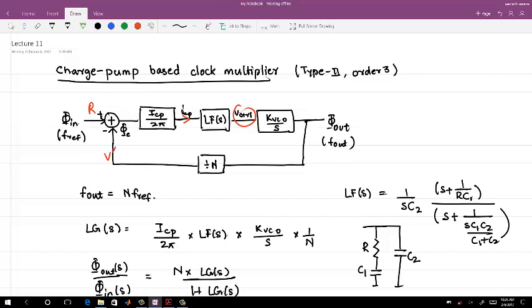And these delays will control when the final edge is coming, right? The way I plot it is, as soon as the reference goes high and the V up goes high and the down signal goes high, ICP changes instantaneously, but that doesn't happen. So all that delay can be modeled. I think you might be familiar with this part, that the delay can be modeled with a transfer function of e power minus std, where td is the delay in the whole loop.